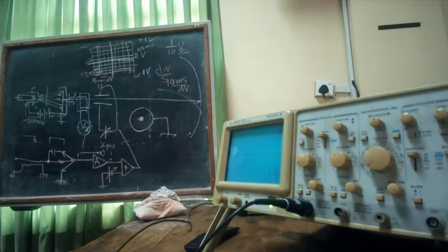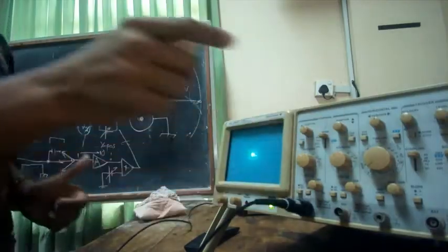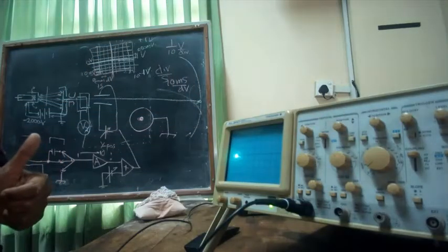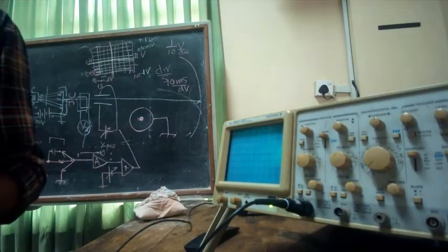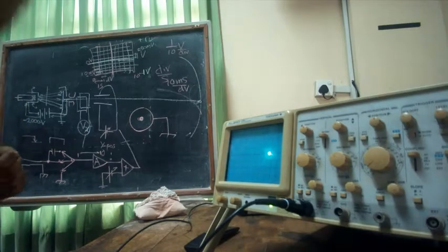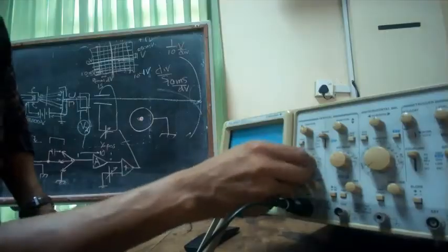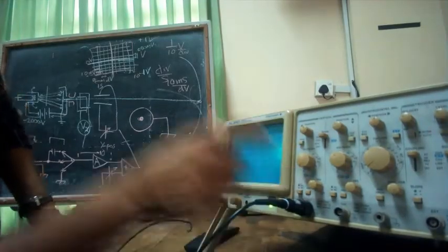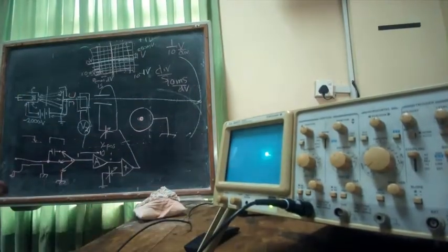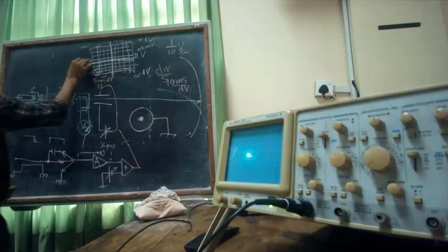Now there is something called volts per division. So division is what? Division is 250 millivolts. That you can't change. Now whatever value that you want here, let's say I have put it into 5 volts per division. That means this should be 5 volts.